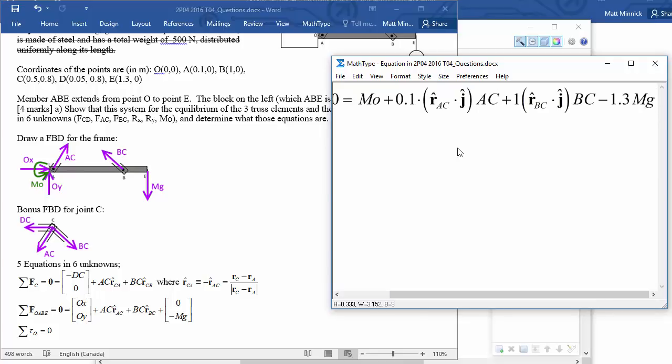Now, a couple things. We didn't have to multiply this by any sort of vector thing to get its component because it's already perpendicular. All of mg is going perpendicular to the line to that force, so it's like a sine of 90 degrees. These ones, by extracting the vertical component, it's the same as taking the sine of the angle they make with the moment arm. The forces right at the origin don't create any torque about the origin.